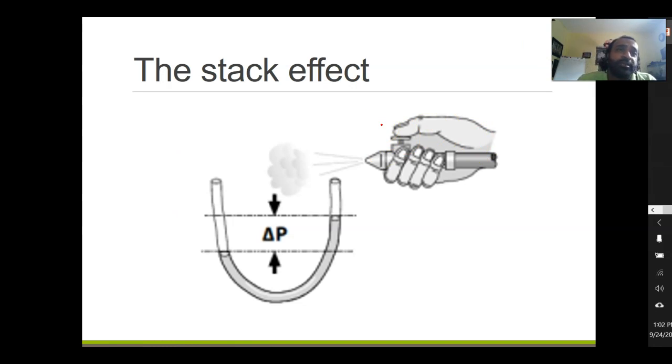So think about that, and think about the chimney. If you have wind, probably the chimney has a lot of negative pressure, and it will pull air from the house. That's why on a windy day you don't want to use your fireplace, and you want some kind of a gate or a door to close it.